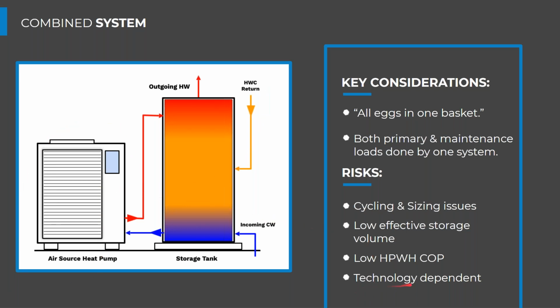So how hot of water can I take into this heat pump? Some, that limitation might be 100 degrees Fahrenheit. Others, that might be up to 120 degrees Fahrenheit, but only when the ambient air is warm. So if I have 115 degree water or 110 coming back, that might be at the limit of the heat pump or very close to it. In some cases, it's going to be above it.